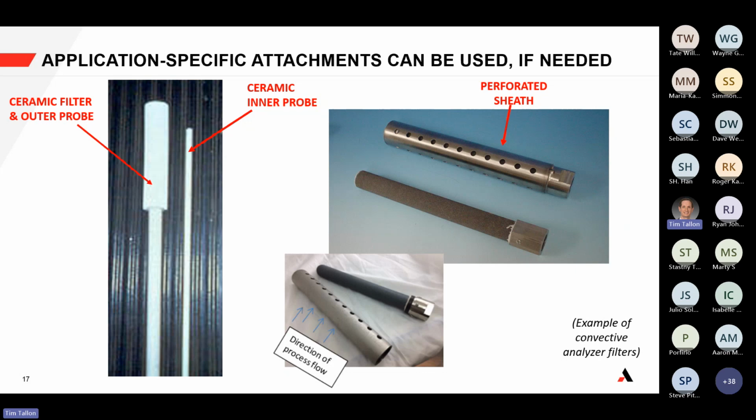And then with the other filter, you could just put it in vinegar and let it soak. That tends to be one of the good solutions that we've seen. There are other solutions too that you could use, depending on the type of process itself. But having two filters is one quick and easy way to change the filter and keep you up and running on the process. Typically you could just submerge it in a solution and it will help remove any of the particulate so that you can reuse it in the future and use it as part of the cycle.